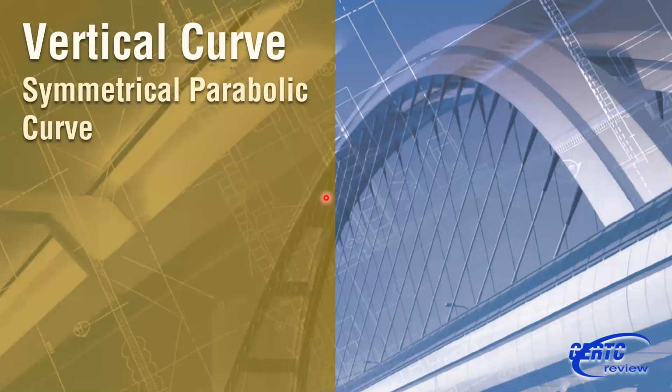So we will discuss vertical curve, symmetrical parabolic curve. So what is this? Where is this used? This is used to connect two different grades, vertical, not horizontal. So we use a parabolic curve, not a circular curve, for the very simple reason that the parabolic curve is the only curve that changes in grade at a uniform rate. The grade changes uniformly with respect to the horizontal distance.